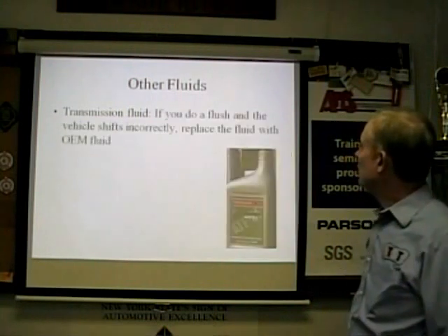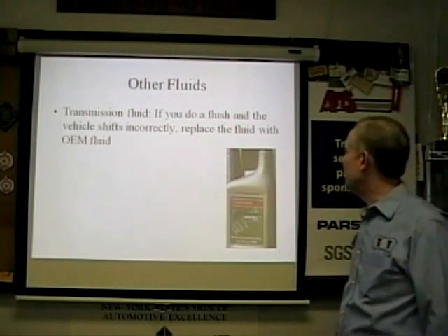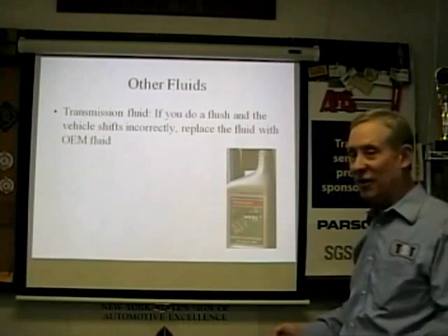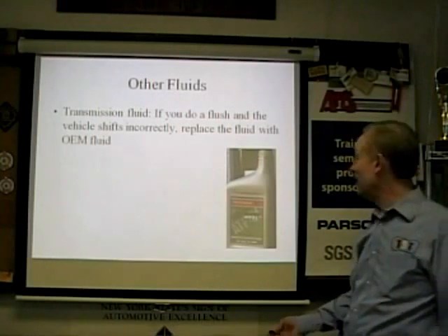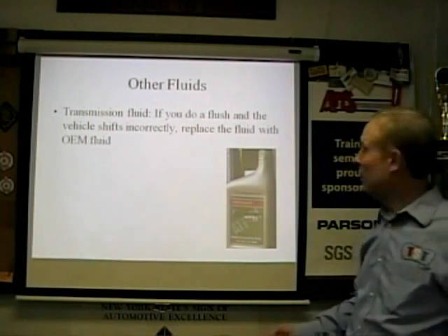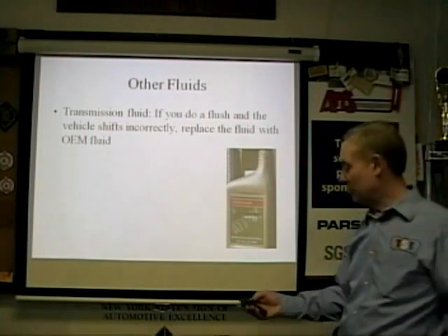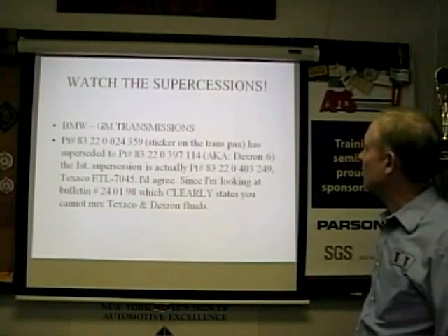All right, transmission fluid. If you do a flush and the vehicle shifts badly, put in the OEM. If there's any kind of an issue, put in the OEM. If you're not sure, put in the OEM. Is that a Honda bottle up there? Honda Genuine HG. There you go. They bang you for some money, but as a professional, you've got to put the right stuff in. And you mark it up, you get whatever your discount is. You've got to do the right thing.